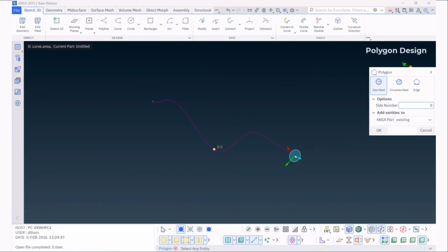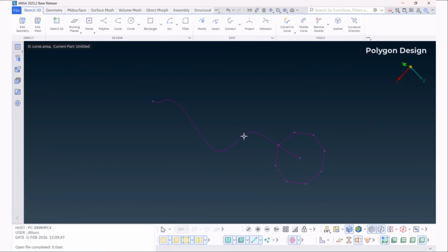On a pre-existing curve, simply hover and select a point to create the polygon, or at the endpoint, click Tab to switch to selecting the orthogonal plane. By clicking spacebar you can manually set the radius of the polygon. Then fill the polygon and mesh it.